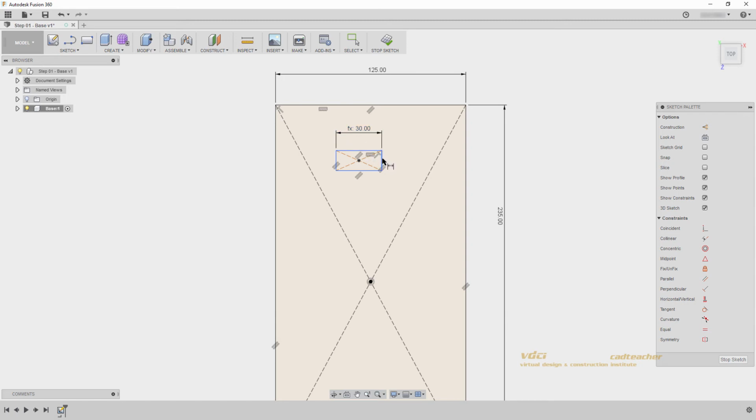Now I want to change this parameter, so I will start typing in T for thickness. You will see that part width also appears as one of my options because T is found somewhere in its name. If I name all of my parameters with long names, because the word width involves a T and a W and a D, all of those names will bring up this parameter as a suggested parameter. By keeping them as 1 or 2 letters, only the expected parameters will appear. So go T, enter, and you will see